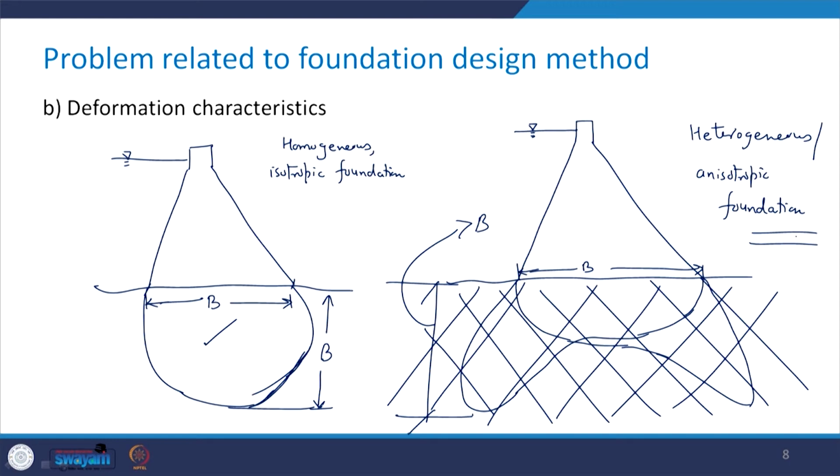The moment these pressure bulbs extend to a larger depth, your deformation characteristics will depend on these things.